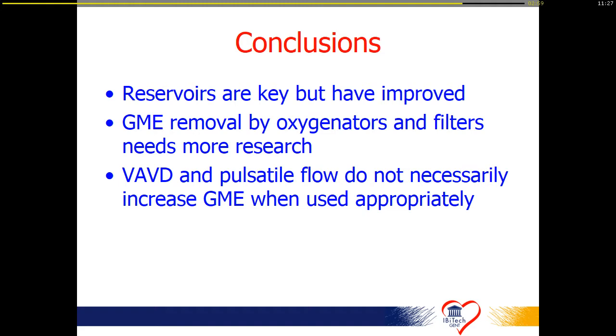Because what is forgotten by a lot of people is that the 10 micron, 20 micron, 30 micron, 40 micron bubbles do not actually get out of the filter. They are not purged. They remain against the screen. So actually they are removed by diffusion over time. So the only ones that will be going through the purge line and the reservoir are the bigger ones, which is, let's be honest, probably a very low number based on whatever data are available.